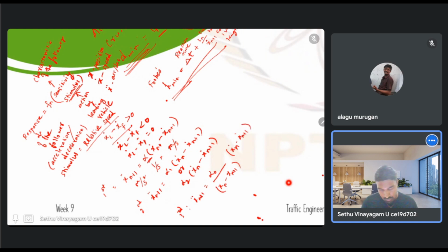Okay, so now the sensitivity part, it is a function of the spacing itself, right? So what happens when the spacing increases? The denominator will become large and the sensitivity term as a whole will be smaller. Alpha naught is still a constant, so alpha naught by spacing will become smaller when the spacing becomes large, so sensitivity reduces. And when the spacing becomes small, alpha naught by the smaller spacing will be a large value, so the sensitivity increases when the gaps reduce.